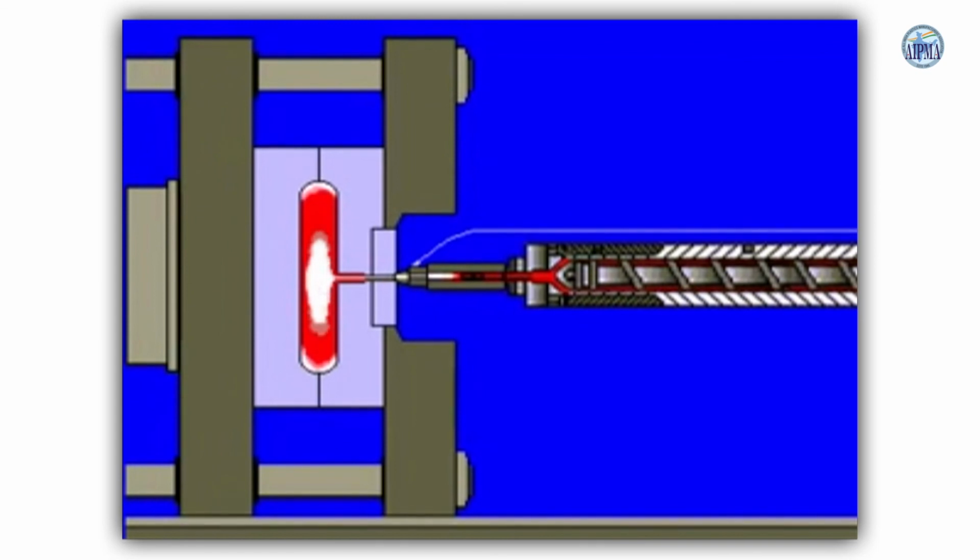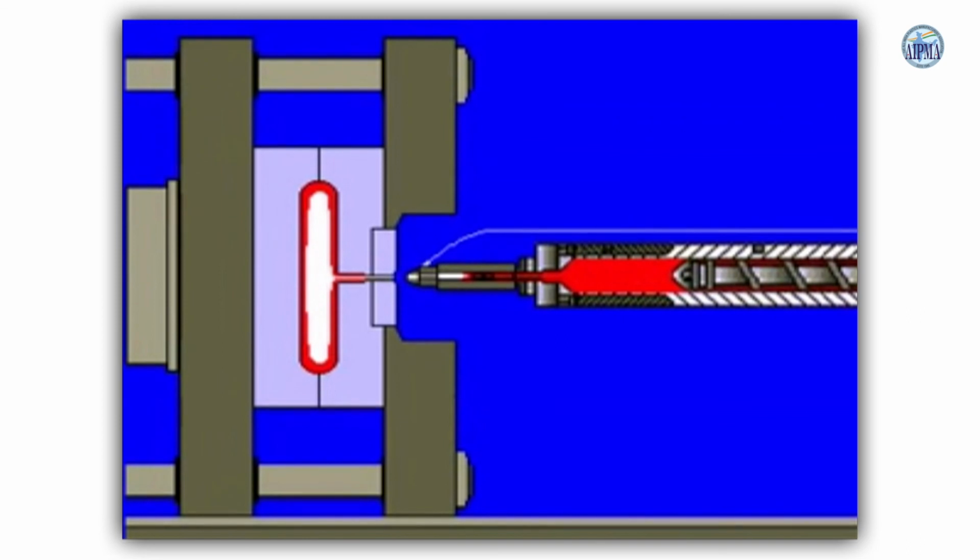The pressurized gas pushes the molten resin tight against the cavity walls until the part solidifies, and the constant, evenly transmitting gas pressure keeps the part from shrinking while also reducing surface blemishes, sink marks, and internal stresses. This process significantly reduces material usage while producing a part with superior structure and aesthetics.